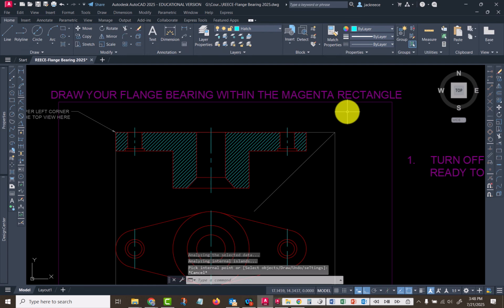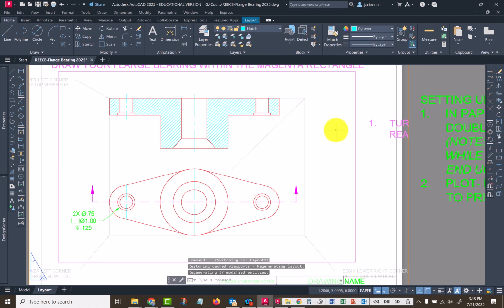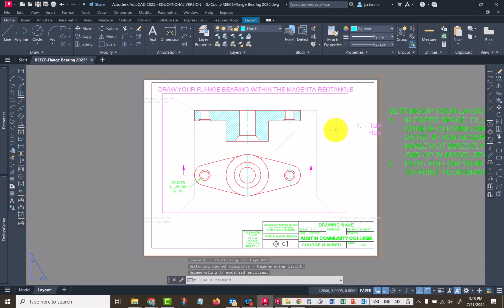And if you remember, back on the architectural drawing, it said a hatch has to have a closed perimeter around it to do its work. So if it didn't work for you, it means you got a gap in your line somewhere. Okay, so you'll dimension this as shown in the current edition of the textbook.